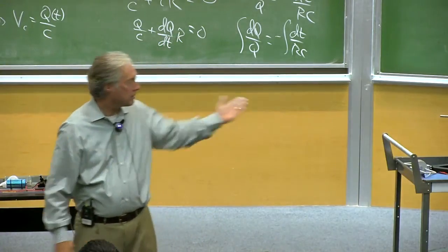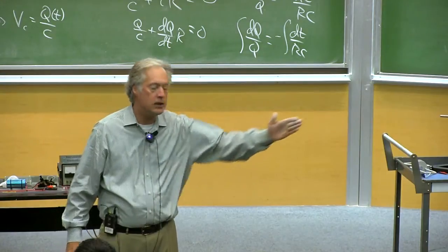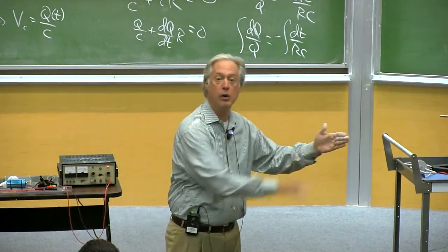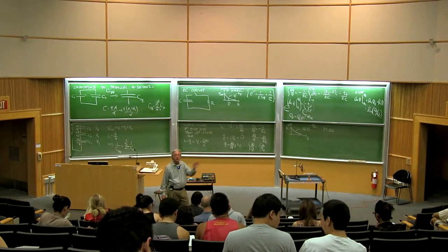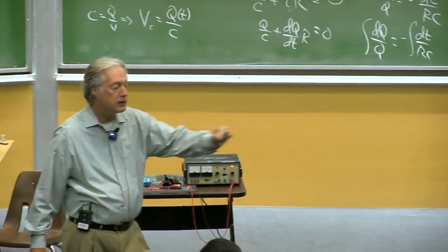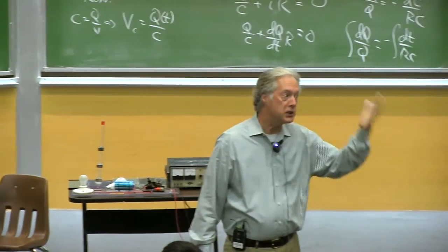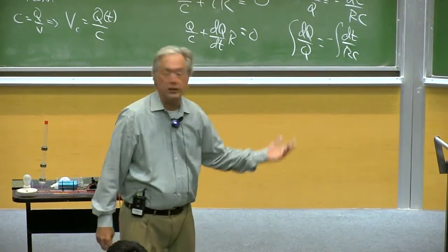The metal phosphor piece is not actually straight. It's got a little curvature to it, so as it scrapes off the beam, it can get a little further down. So what you're seeing there inside that tube is electrons have been accelerated and travel along, and where they hit the phosphor, they have enough energy in the beam to light up the phosphor. It only takes a few volts in energy to do that.